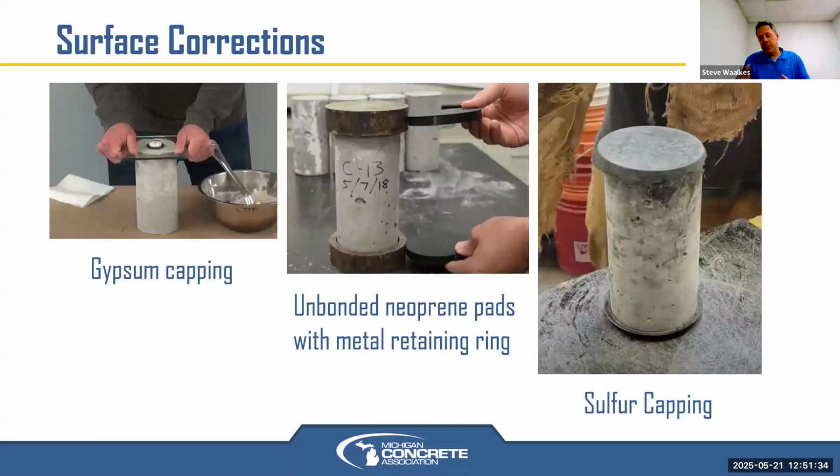Like when can we just use plastic? Do we need to use blankets? How cold is it getting? So what protection measures do we need? It depends on how thick it is and how much heat it's giving off and the mix design and all these different things. But it also comes down to inspection, ensuring that the contractor is doing that and holding their feet to the fire and making sure that they're doing what it says in the specification.